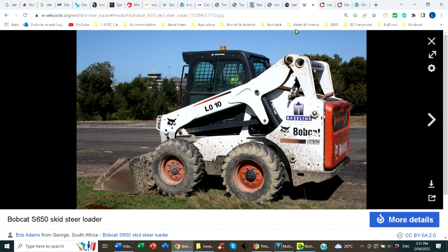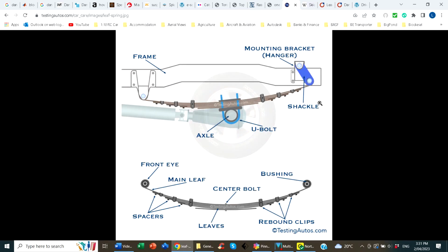If we're going to talk about real springs, the simplest one is a leaf. And here's a typical leaf spring installation. These things get a bad rap when compared with coil springs. The reality is a well done leaf spring can almost equal a fairly lousy coil spring design.